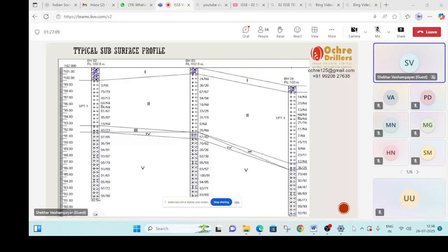I should take here, either that layer dips. I cannot place it here at 9, 0. So I have to take my layer. In this borehole 2 and 3, the depth would be about 91 RL, and in this case it will go down to 85, 86. Okay. So that's how you select.